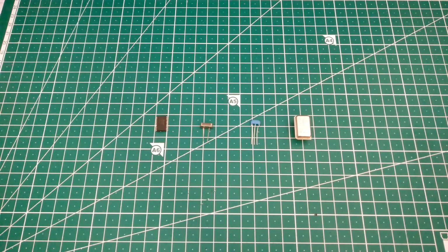However, this thing is significantly bigger than just a crystal. Even the SMD versions are significantly bigger than the SMD crystals. And it's 4 or 5 times more expensive. So, yeah, it's not an optimal solution, but for some situations you might need it. And there are other digital microchips which do require clocks, often enough if they have very few legs. And this can be a solution for those, although it is possible to output the clock from the microcontroller itself and then feed it on to such circuits.